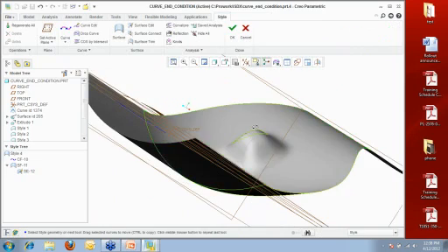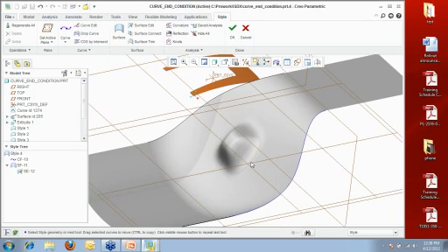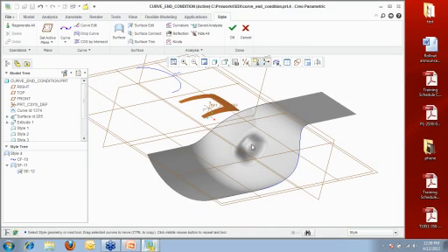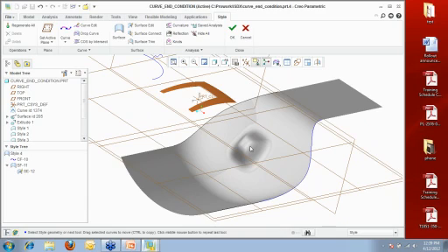And now what I've done is added in a fairly complicated add-in to this surface fairly simply. If you tried to model surfaces like that and the angles and trying to put that in, it's not that easy. Having all these rounds that exist, I just picked it, put on the surface edit, picked a few points and dragged them out. Okay, you can't attach those points onto other entities with the shift button. And again, it's just nice surface editing capabilities within the tool that come along with it. And if all you're looking for is to drag some things around and do some of that stuff, it makes it nice and pretty.